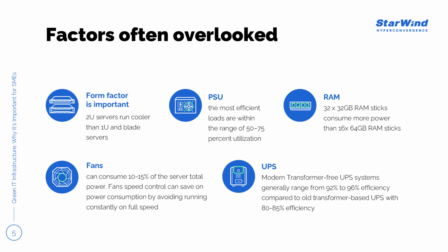So the load is powered by the bypass line, with the inverter inactive but ready to take over if there is a mains supply failure or fluctuation. This can of course affect the reliability, and so it should only be used at proper times, for example, overnight or out of hours when critical loads are inactive.